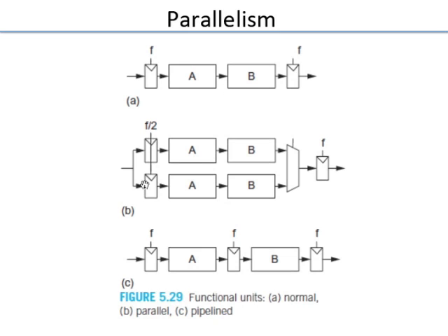Of course, you see two things here. One is you need to distribute the information once every alternate cycle: it goes up, comes down, goes up, comes down. Similarly, you have to collect it out here. So there is an overhead of distributing and collecting when you go parallel, spatial parallelism. In temporal parallelism, the overhead is additional sequencing elements.